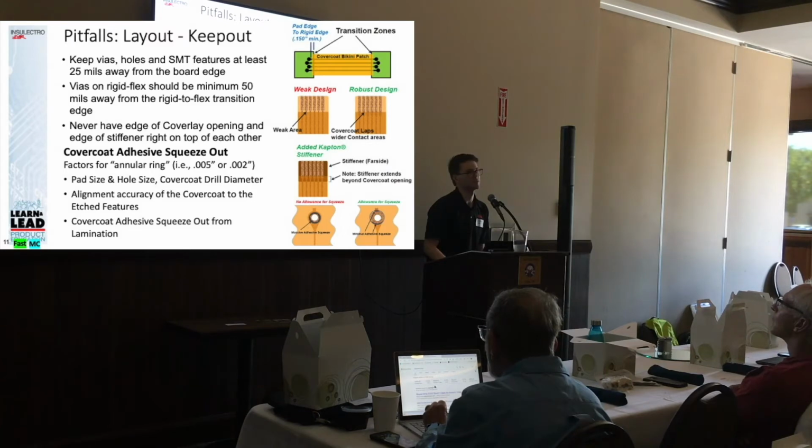Most epoxy resin systems or rigid resin systems are anywhere between 160 to 260 degrees centigrade before they even hit that Tg moment. What this means is that during the fabrication process, as well as during our solder float and final validation, the acrylic adhesive can expand and cause problems. So in the fabrication process, we pull those acrylic adhesives outside of the rigid section.